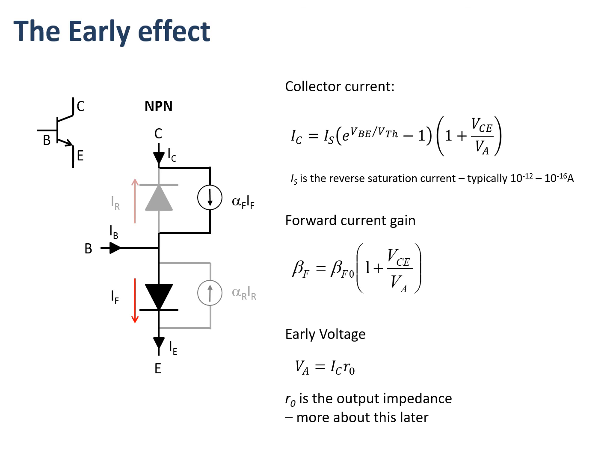That will enable us to calculate the collector current more accurately where we feel that the Early effect is in play. What that also does is modify our gain as well. So our gain changes as well. And we'll see later on that this will also impact the output impedance of the device. So these are important considerations in some circumstances where the Early effect might cause us to redesign our circuit slightly.